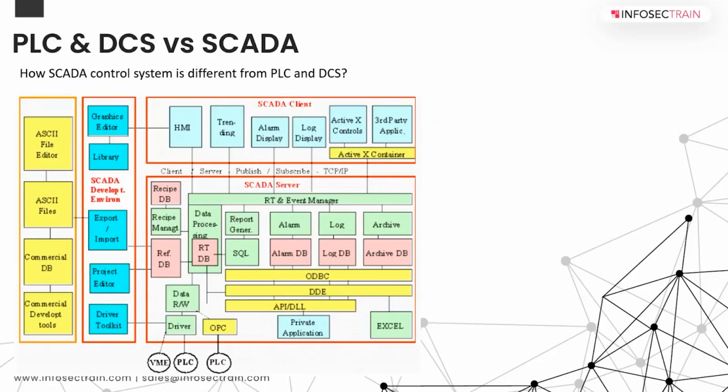When we talk about DCS, it's process-oriented, process state-driven, while SCADA is data gathering-oriented, event-driven. This is a very important distinction that you need to understand. DCS will contain one or hundreds or more controllers to implement advanced process control, while SCADA systems cannot carry out advanced process control techniques.